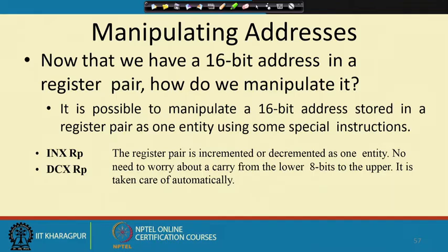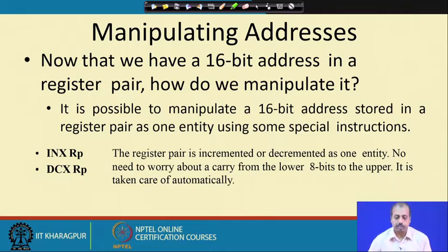INX will increment the register pair by 1. That way, it is possible to manipulate a 16-bit address stored in a register pair as one entity. Using a special instruction like INX RP, the register pair is incremented as one entity and the carry is already taken care of.